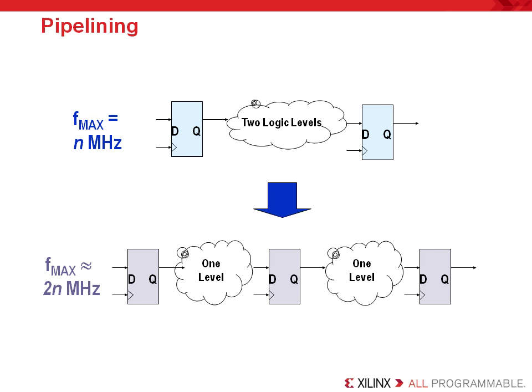While there are a number of ways to improve the performance of an FPGA design, and they can vary significantly by design, one of the most important ways to improve the speed of a sequential design is to pipeline critical data paths. In this example, we have a data path that has 2 logic levels. That means that the worst case path goes through 2 LUTs in series. To break these logic levels, we need to insert a pipeline stage. A pipeline stage is just a bank of registers to break up the data path.